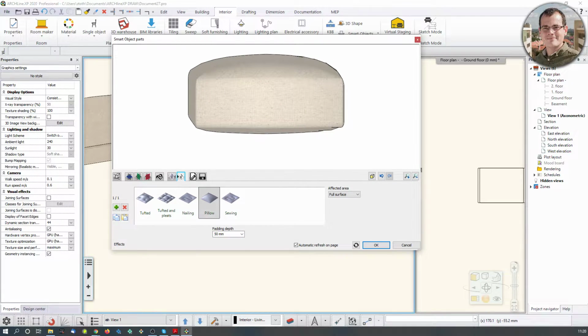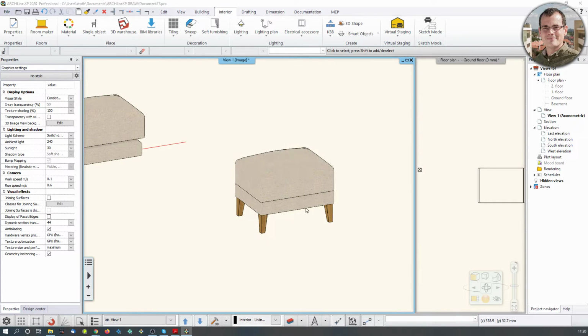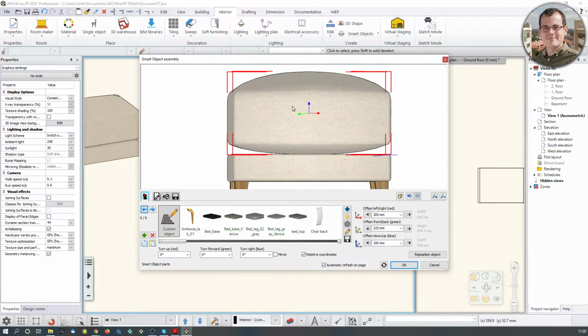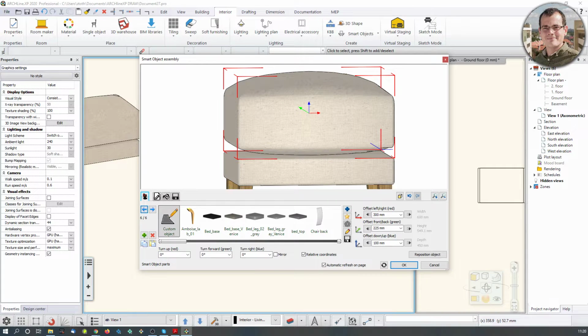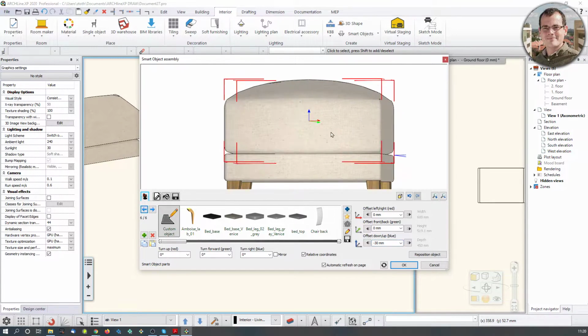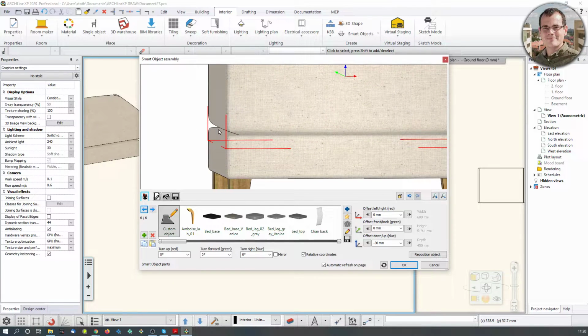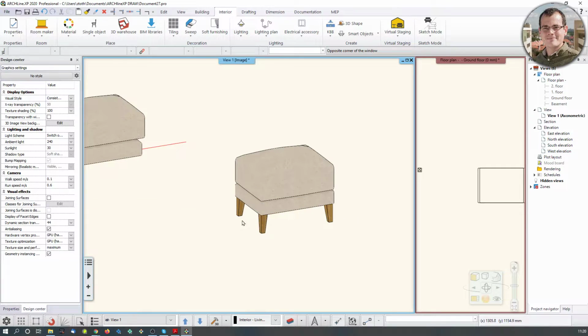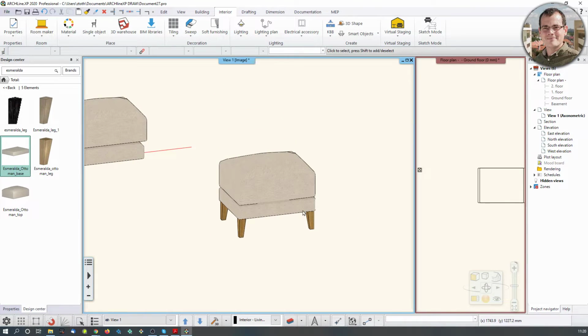Okay, this looks much better. Let's just hit OK. Yes. And now the problem is that because of the pillow effect, the object is sort of extruding itself out. So what do I need to do? I need to sort of decrease the blue axis. Let's say minus 30 millimeters is on my guide. So that way it's pushed in, but it's a much more believable effect. So let's just hit OK. And now I have the object the way I want it to.